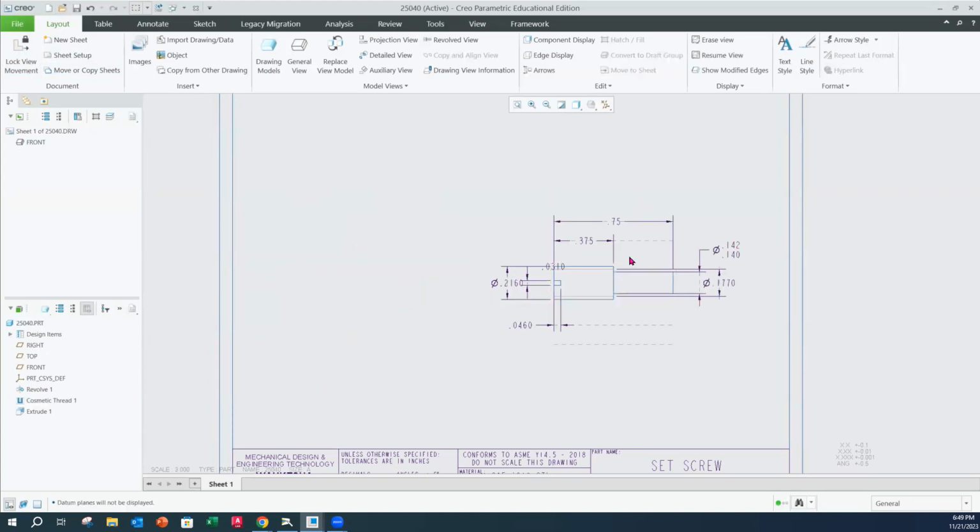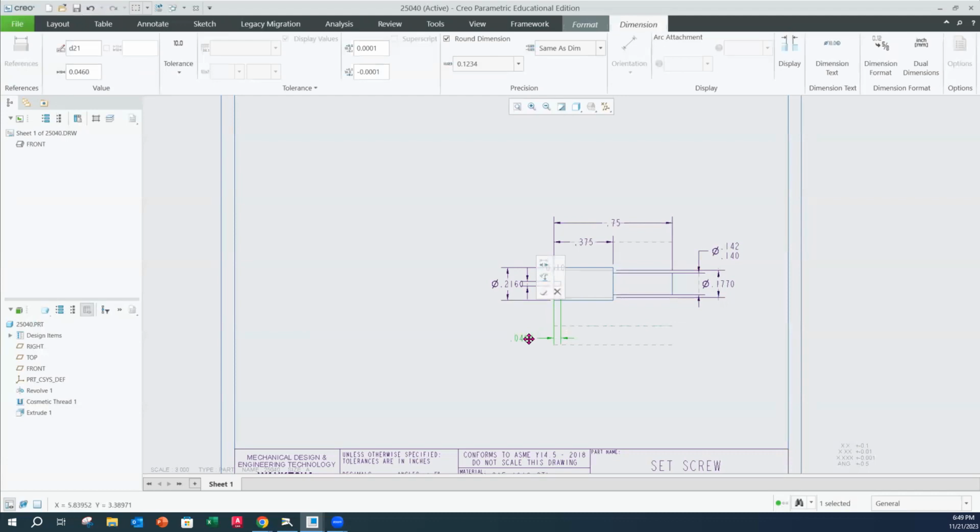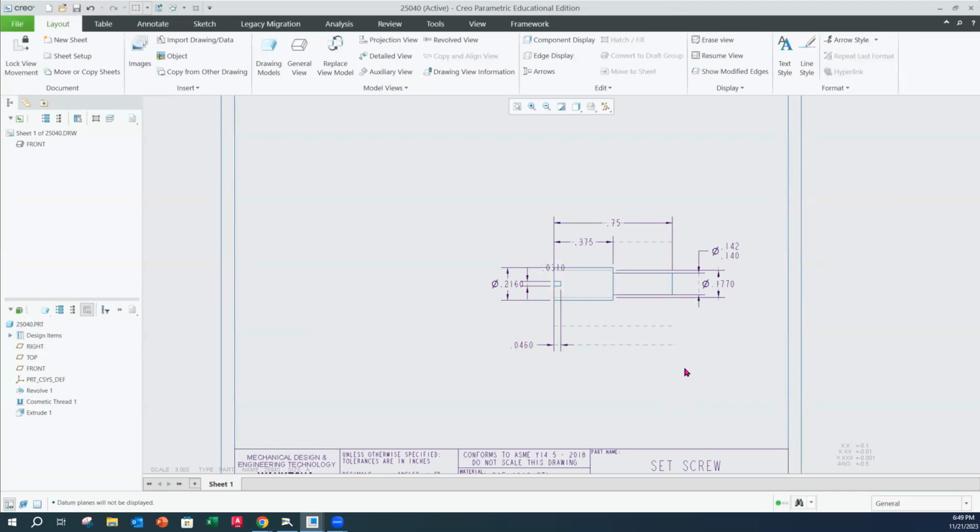Okay. Now, something you're going to notice here as well, there are these dotted lines. These dotted lines are there for reference, for you to place your dimensions around the part. They're a nice guideline for not getting too close or too far away, and for having proper spacing between. The dimension is a 1/2 inch from the edge of the part, and then it's 3/8 of an inch between. When you place dimensions, you'll be able to snap to these lines. So if I select a dimension here and move it, when it gets close, it snaps to it. That's a nice feature because then everything is even throughout. So that's what those are.